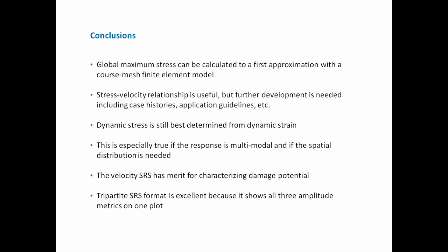Dynamic stress is still best determined from dynamic strain. This is especially true if the response is multimodal and if a spatial distribution is needed. The pseudo-velocity SRS has merits for calculating damage potential. And the tripartite SRS format is excellent because it shows all three amplitude metrics on one plot.